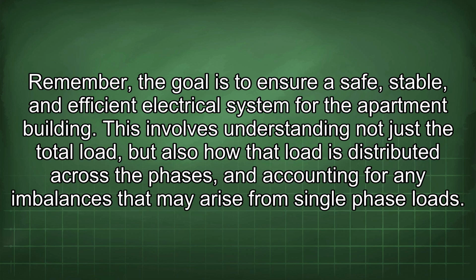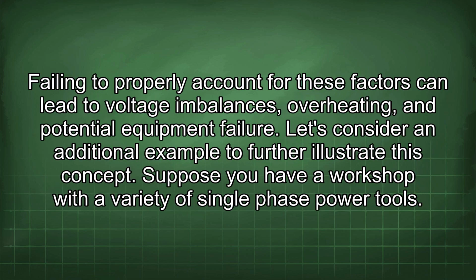This involves understanding not just the total load, but also how that load is distributed across the phases, and accounting for any imbalances that may arise from single-phase loads. Failing to properly account for these factors can lead to voltage imbalances, overheating, and potential equipment failure.